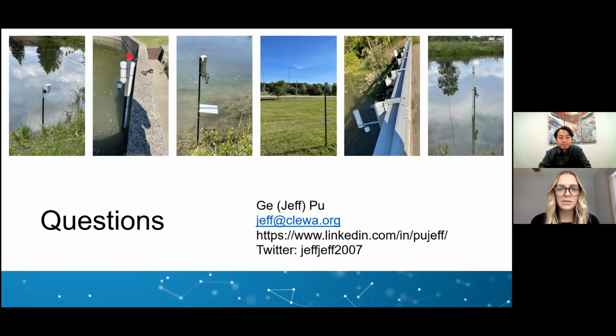Great. And then Ronald's asked about batteries and how often they need to be changed for the sensors. Yeah, so as I mentioned before, these transmission units have a 3-volt battery inside of them. They are like this big, and you can essentially connect to a sensor and then put these in the field for years. In our case, we have utilized them for 2 years or so before we have to change the battery out.